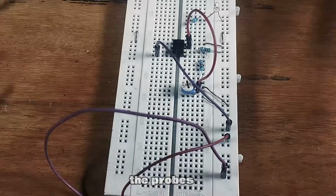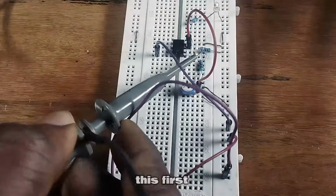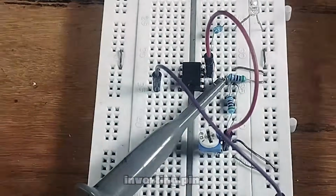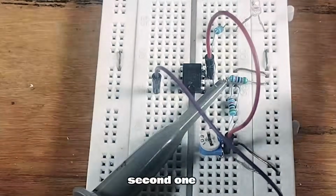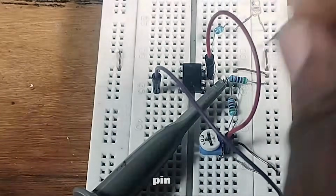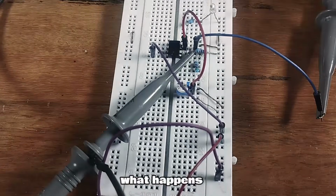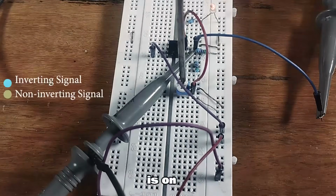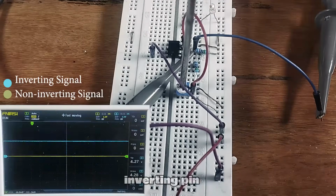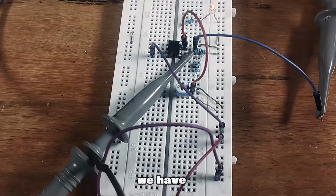So first, to connect the probes of our oscilloscope. All right, so this first one goes to the inverting pin, and we have a second one at the non-inverting pin, so we can get to see what happens with both pins when our LED turns on. So we turn on our power supply, we see our LED is on, and that's because once you have the non-inverting pin higher than the inverting pin, we have our output saturate and we have our LED turn on.